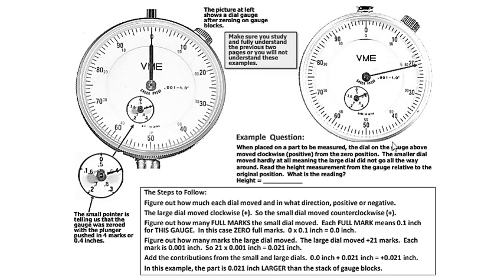So now this is just showing you the measurement steps, how to do it. First, of course, we zero out by using the gauge block. Of course, we know the size of the gauge block, and we zero out one end. So after you zero out and swap your object, you should be able to get either a drop or an add, either on this side or this side.